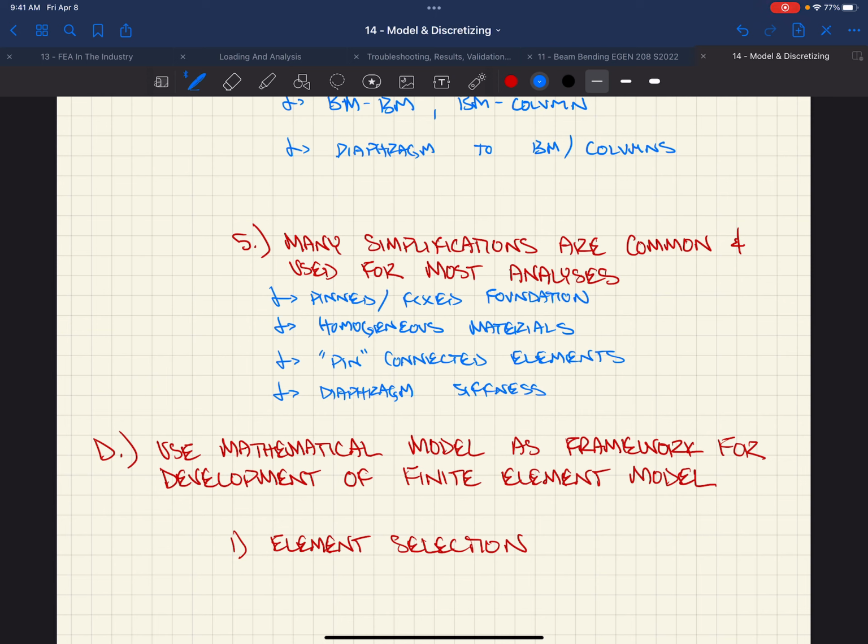Well, doesn't that depend on whether your diaphragm is rigid? You're going to have to be pretty deep in order to be rigid enough to start displacing your shear walls like that, right? Otherwise, the load just gets attracted to the other shear wall, because the diaphragm just deflects. Yes. And in ASCE 7, is it ASCE 7?